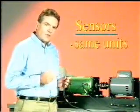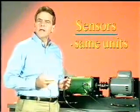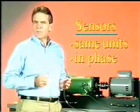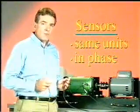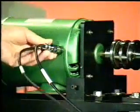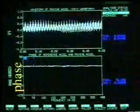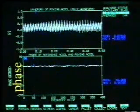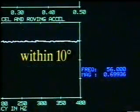First, the two sensors must be using the same units, such as G's. Secondly, the sensors must be in phase. That is, they must read the same phase angle for a given point. To check for this, place the two sensors side by side on a machine and check the phase between the two. They should read exactly the same or within 10 degrees of each other.